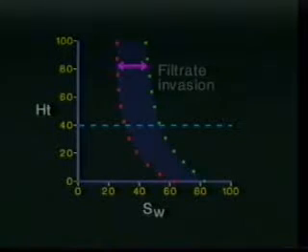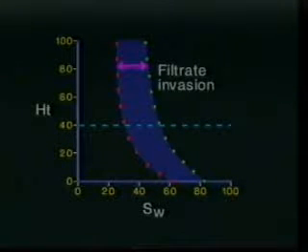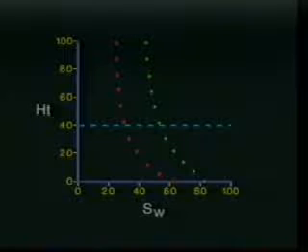The difference between the two represents filtrate invasion. We can draw an obvious conclusion. If you want an accurate water saturation, use an oil-based fluid. If you want an accurate oil saturation, use a water-based fluid. In our company, we have a more specific policy.